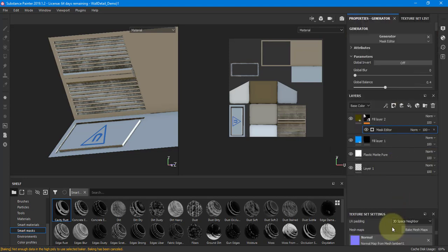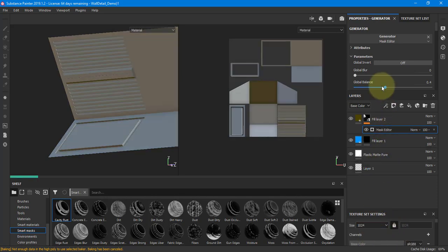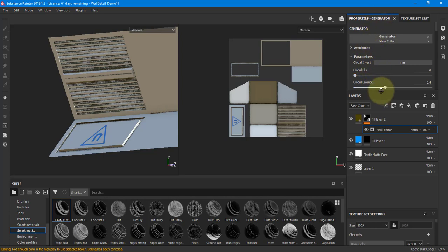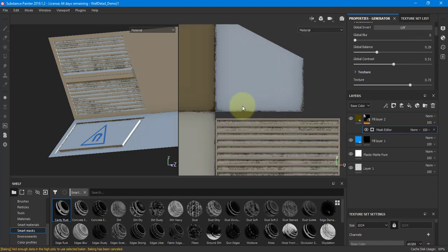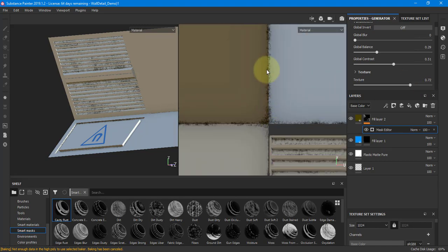Let's just drop that there for a second. Let me find my document size. All right, so I'm lowering my document resolution just so as I play with this, it goes a bit quicker. There we go. Okay, so now we can see very quickly we can adjust what this is looking like. We can also pull the contrast back or pull the contrast up, or we can play with the amount of texture that's inside there or whatever. And you'll see even on here it looks really cool where everywhere we have these things that are touching or at these corners, it's creating this really cool noise pattern.